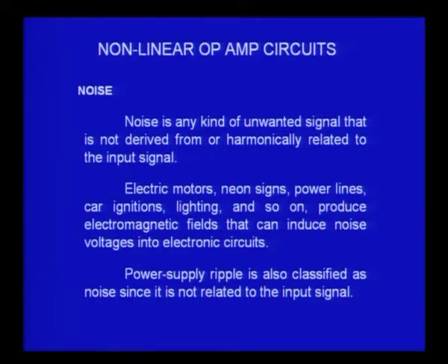All these noise voltages are random, and therefore, they can either increase or decrease the input voltage randomly, and if it increases or decreases by more than 150 microvolt, the output will change even though my input voltage is not changing, purely because of the noise voltage. The magnitude of the noise voltage is exceeding that 150 microvolt limit, and therefore, the output switches automatically without waiting for the input to change. This is an undesirable effect, we do not want that to happen.